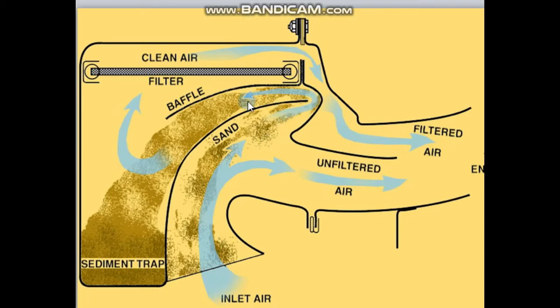The venturis and the bends are used to accelerate the flow of incoming air and debris, so the debris has enough inertia that it cannot follow the bends in the intake. This allows sand particles and other small debris to be channeled away from the compressor.